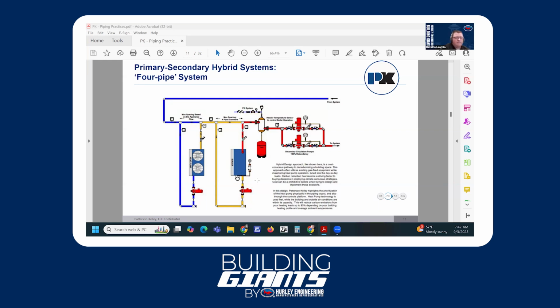In fact, you can designate the temperature it runs at. It can be at a less hot temperature because that helps the heat pump, less lift on colder days. You can do less hot, and that condensing boiler can take care of the rest. It can feather up and handle extra temperature requirement, and they can work together that way.